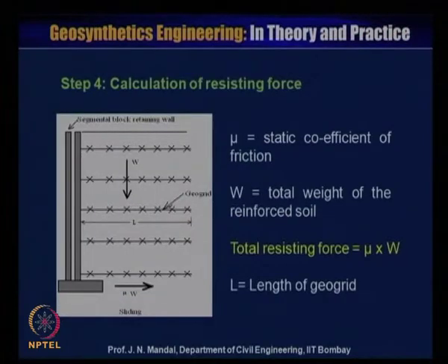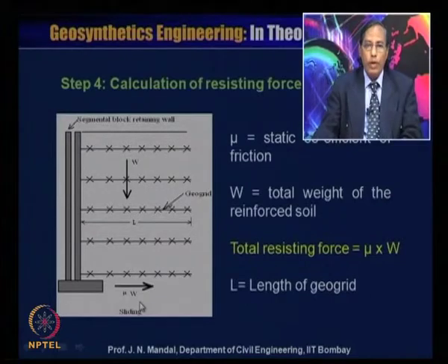Step 4, calculation of resisting force. Here you can see W, the total weight of the reinforced soil, and here the wall moves. This is a segmental block retaining wall. The wall wants to move due to sliding, and it should be resisted. If the weight of the reinforced soil is W, it will be resisted by mu of W. W is equal to the total weight of the reinforced soil, and the total resisting force will be mu of W.